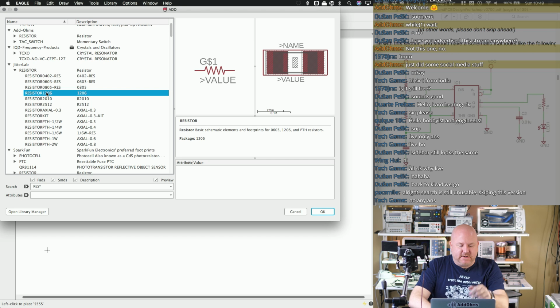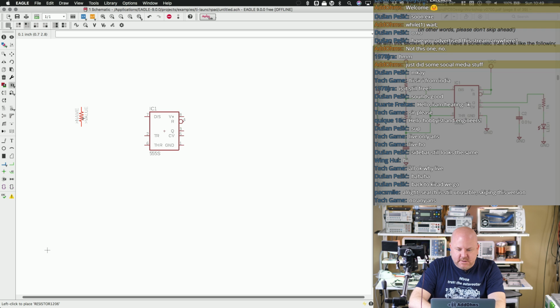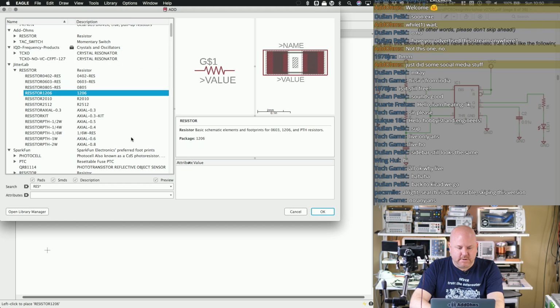So in this class that I wrote, the original idea was that you would actually mill this PCB on a ShopBot. And so I had to design the circuit so that it could be easily milled on one side. I'll show you at the end what my final design looks like, but you did need to use 2 vias because you had to loop 1 wire. All right.